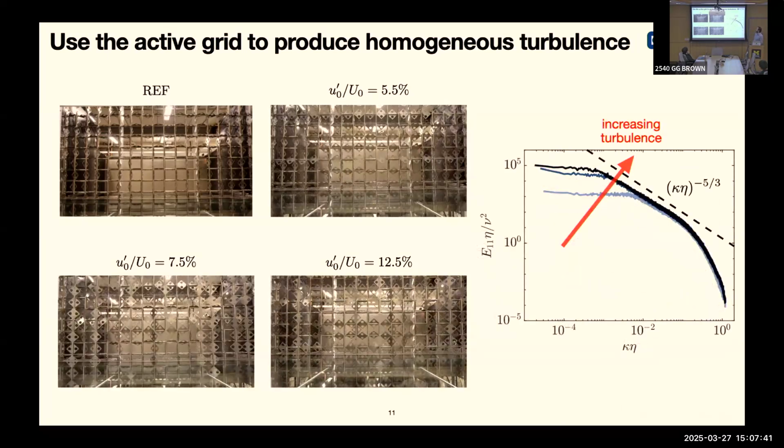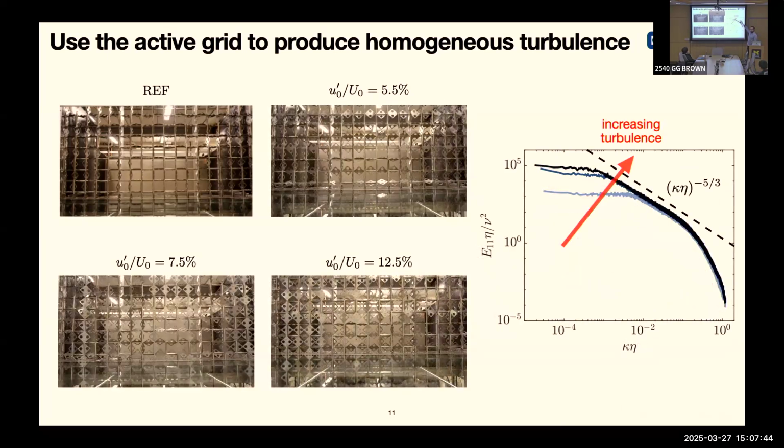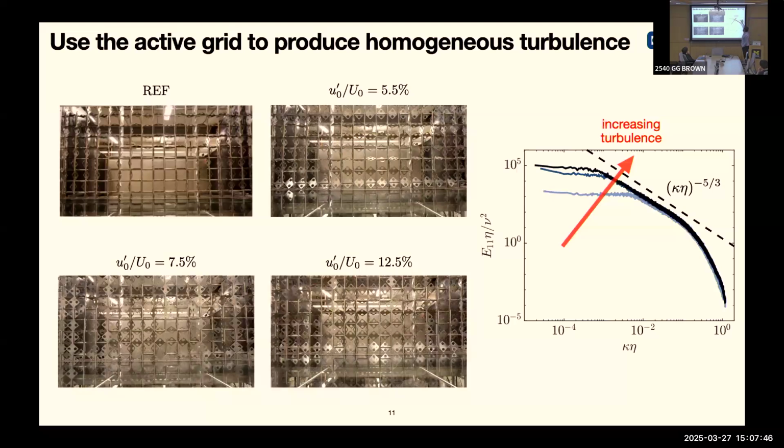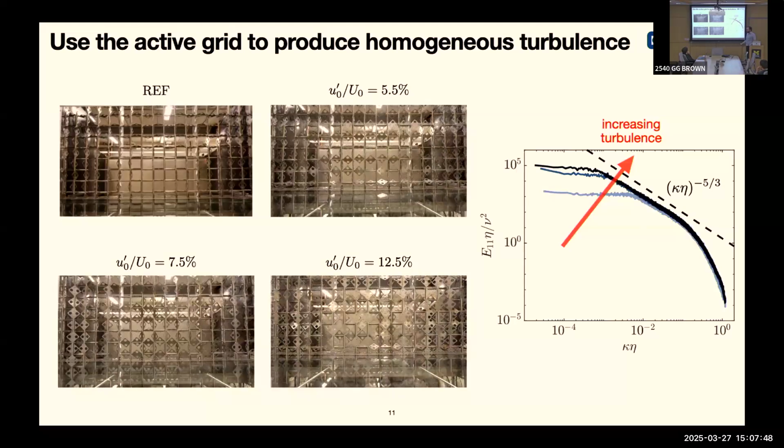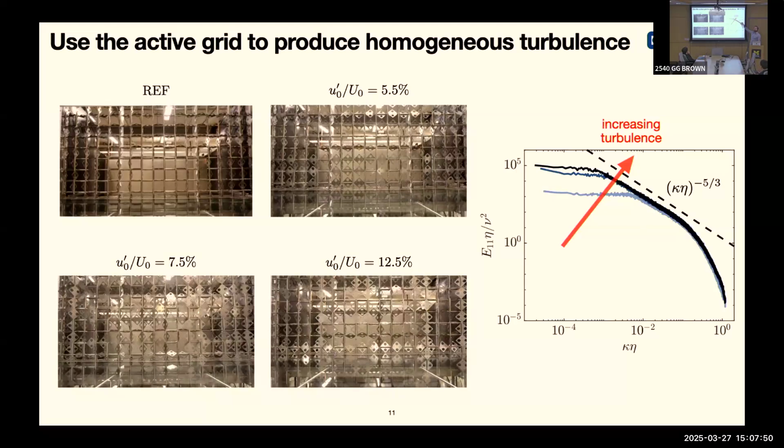And if we do dissipation normalization, we get a 5/3 law, which again, if you study turbulence, this is an expectation we have for what's called the inertial range. So basically, this is giving us a nicely behaved turbulence.